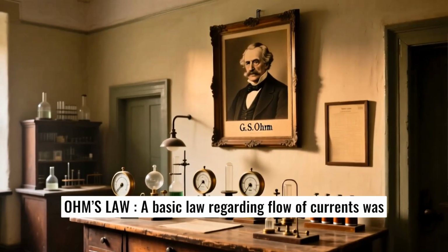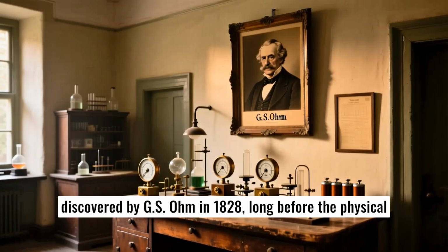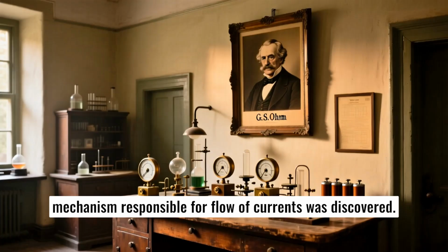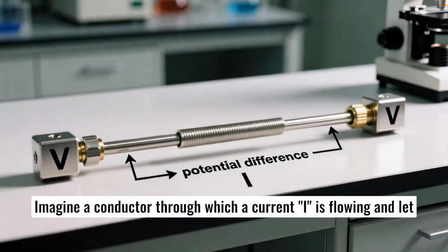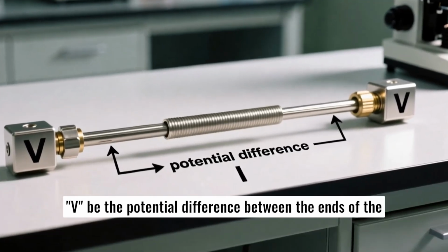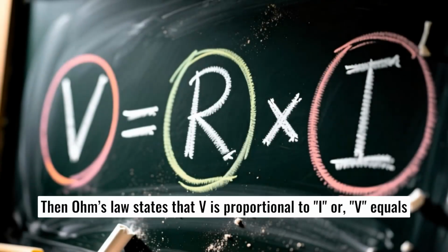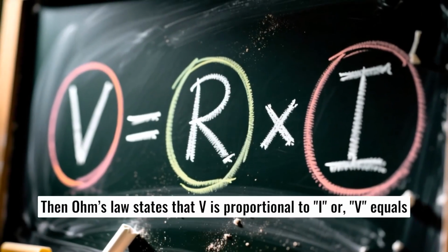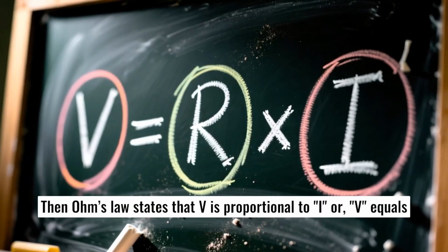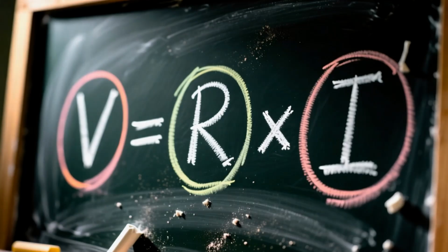Ohm's law, a basic law regarding flow of currents, was discovered by G.S. Ohm in 1828, long before the physical mechanism responsible for flow of currents was discovered. Imagine a conductor through which a current I is flowing and let V be the potential difference between the ends of the conductor. Then Ohm's law states that V is proportional to I, or V equals R multiplied by I, with a constant of proportionality R called the resistance of the conductor.